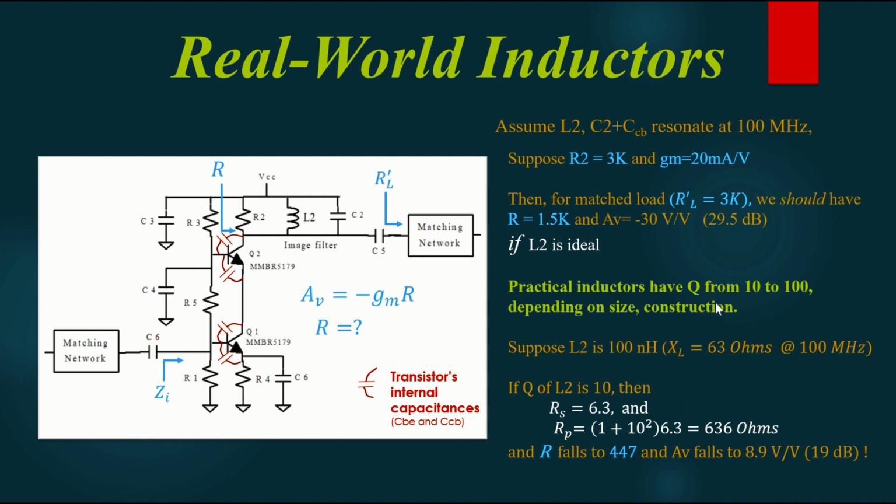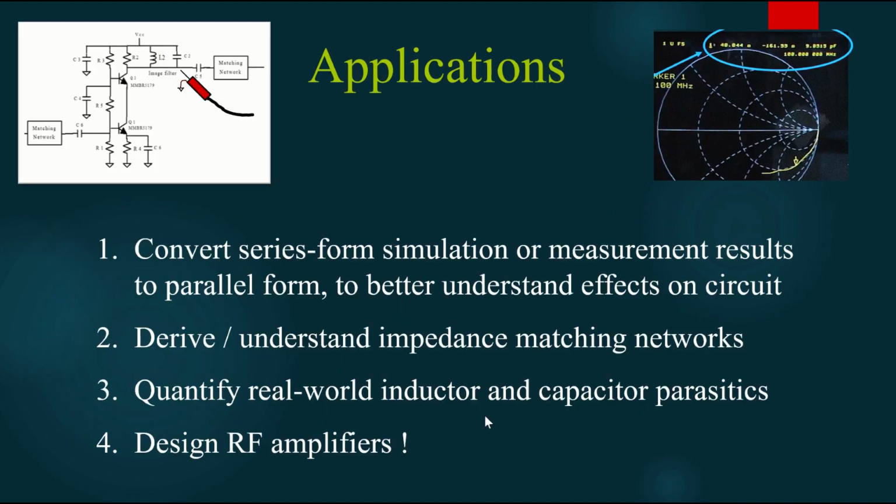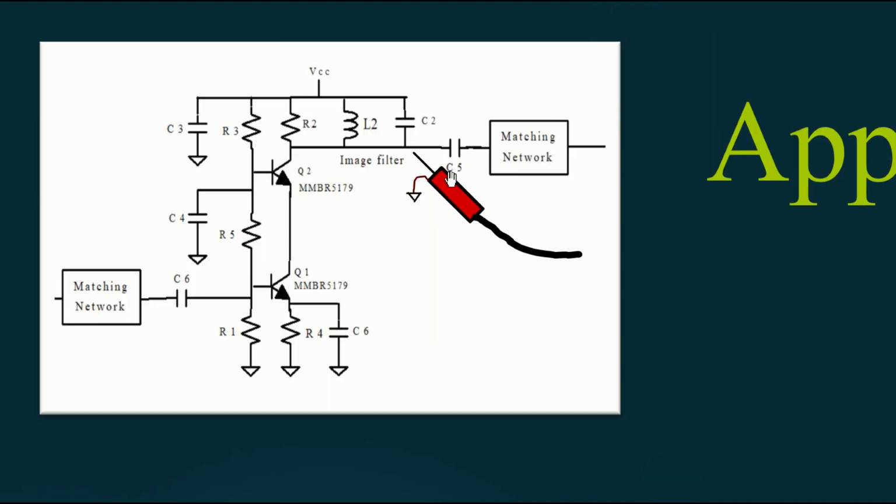Well, we get a better inductor. That's what we do. Now, we could also do this for the capacitor in the tuned circuit, but capacitors are generally much better than inductors. The inductors are the limiting factor typically. Okay, so we've talked about the loading of a probe that you put onto this node, for example. We've talked about how L2 degrades the LCR resonator if it's not a good high Q inductor.